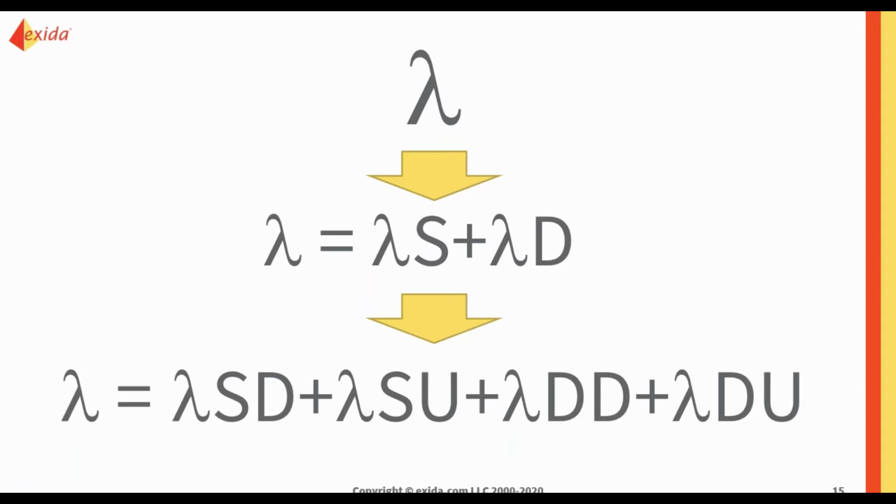But the easiest way to know a device's failure rates or a device's lambda is from the FMEDA, or failure mode effects and diagnostic analysis report, or the back of the certificate. As I said, that lambda total can be broken into safe and dangerous failures. That lambda S represents the safe failure or your spurious trip rate. And once again, in functional safety, those are given in the unit of measurement of FITs.